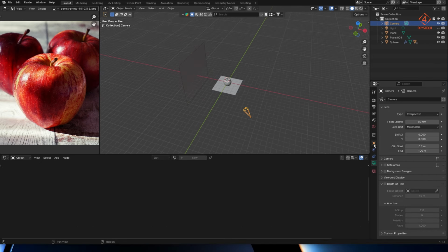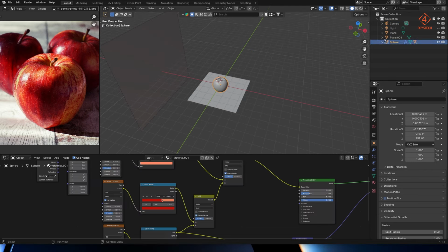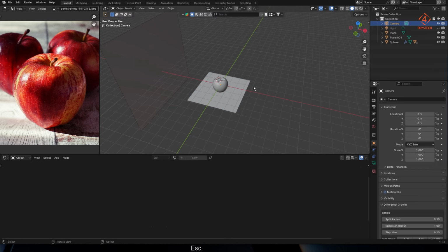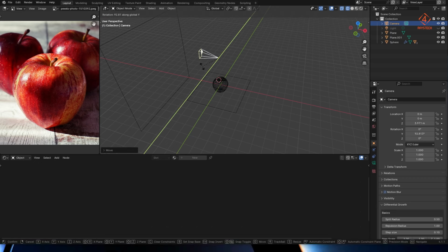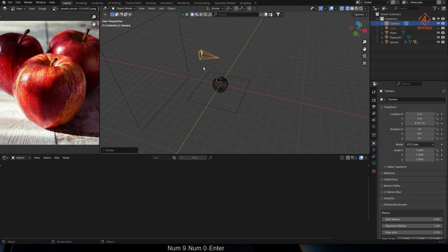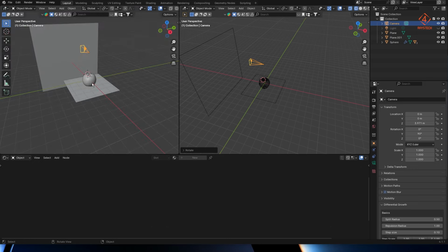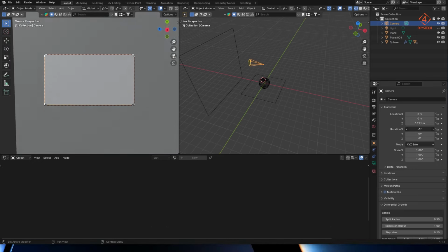Hey, so the camera, let's just zero out everything, so it's at origin, nothing has changed. Now, heading back into wireframe mode, let's move it back on the x-axis, sorry. Yep. Select the camera and move it back. Move it up a bit. Let's rotate it. And in order to see through the camera, we can always press 0. Let's make one more view here and press 0 right here so we see exactly what the camera sees in this viewport.